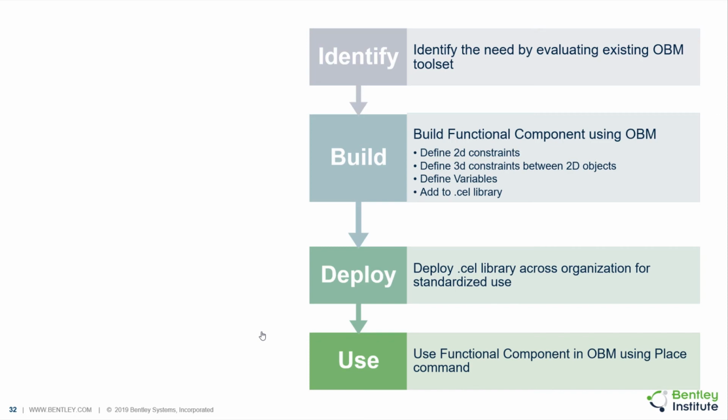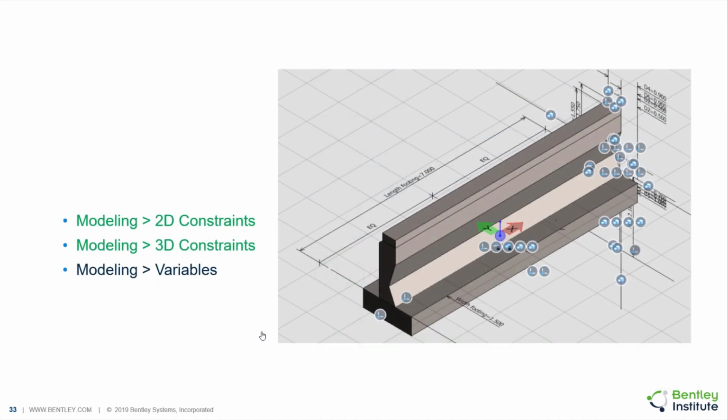The beauty is that when you apply the proper variables to this parametric cell and use it inside OBM, we understand that you are not placing just a cell, you are placing actually a pier, and it goes to go down when you place bearings, for example, right? Or it has to go skew when you skew the angle of the support, right? So you have to think about it, how much constraints you need to apply to your cell, right?